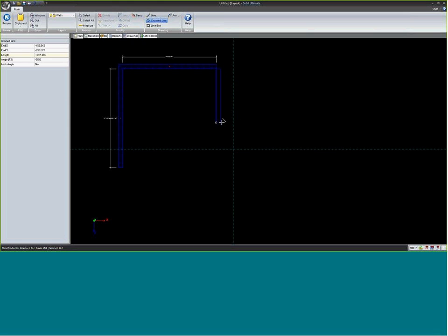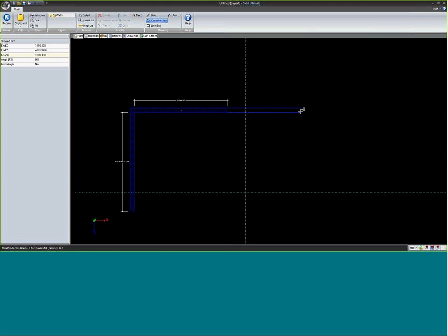Another thing I can do is, if I'm going this direction, I can look and see my angle as it changes. Notice minus 22.5, there's a minus 35. So if you think of angles in drawing walls, straight to the right is 0, and then it goes counterclockwise from there, just like on a protractor. It goes around the 360 degrees.